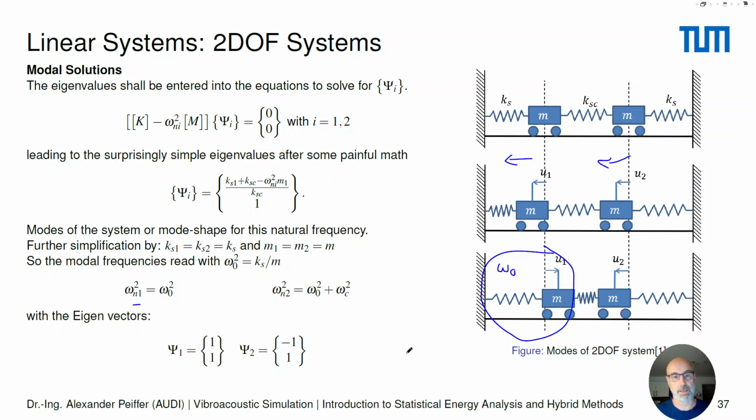So what is the outcome of this? We see that even if we have more complex systems or multiple systems, we still have something like a resonance, and to this resonance a specific natural shape of motion corresponds. And this is the mode. This, as we will later see, is a very important concept for simplifying our multiple degree of freedom systems later on.